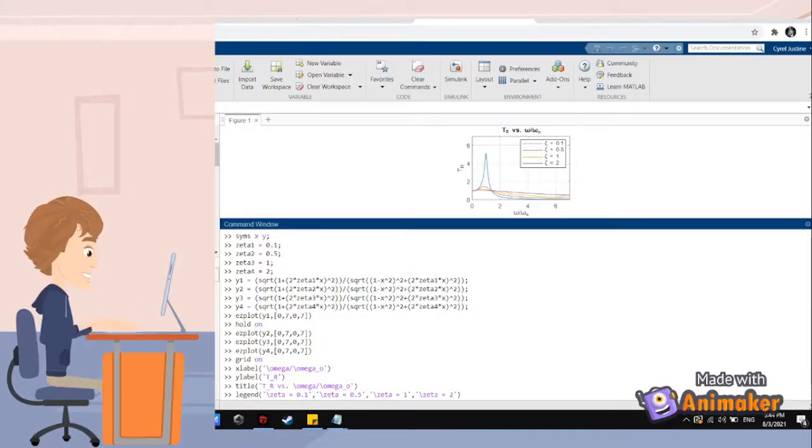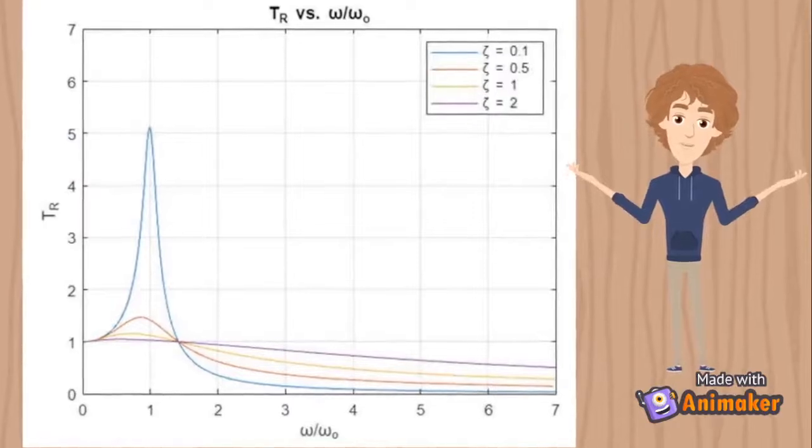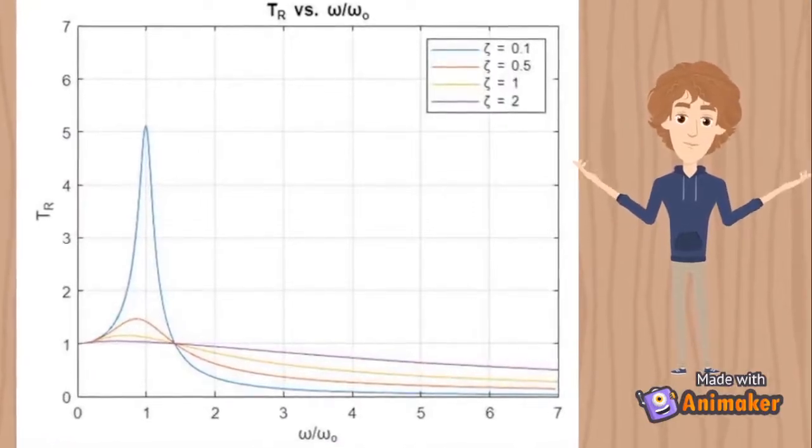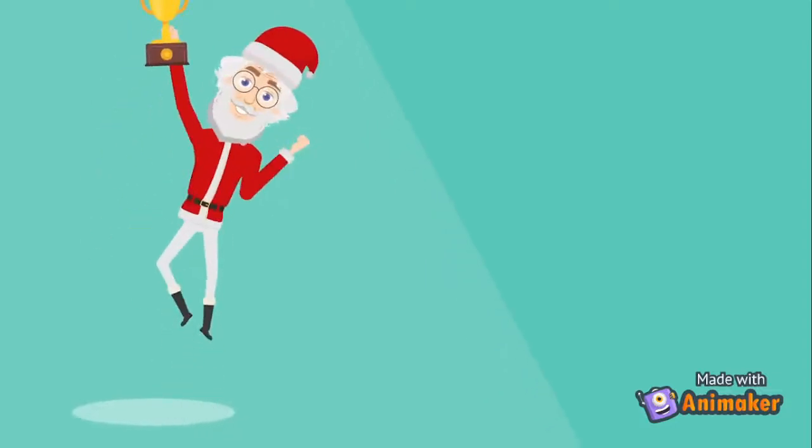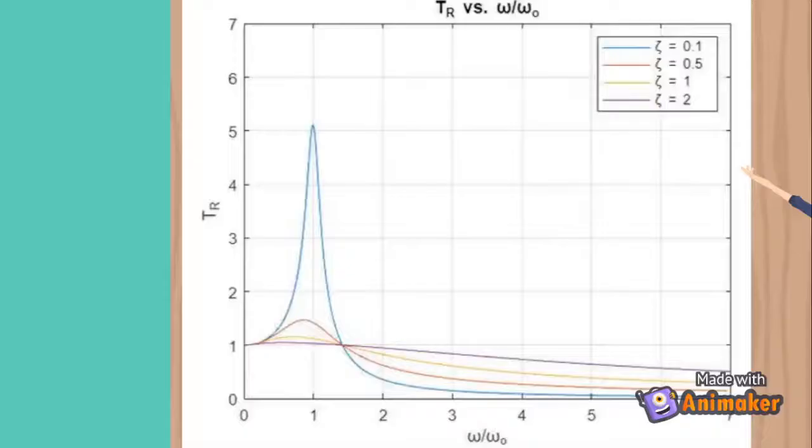Since the isolators are low stiff, the vibration of the source will be easily absorbed and will minimize or even remove the vibration felt on the platform. If high stiffness isolators will be used, then the excitation frequency of the machine will coincide with, let's say, a metallic spring isolator which raises its natural frequency, resulting in a vibrating platform which negates the purpose of isolators.